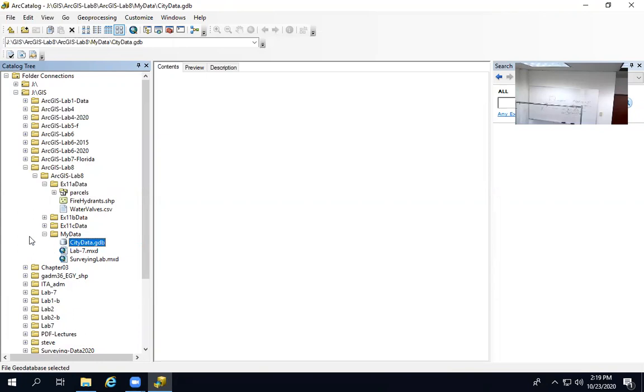Okay, guys? So now I created a container. It's an empty container right here, okay? So that's the second one. Now I want to import data that are already there. Let's imagine that you downloaded a bunch of shape files and you want to import these shape files to your data. Remember something, we learned how to do some coordinate systems. So we want to make sure that the coordinate systems are united. This is one thing that will be taken care of when we do it.